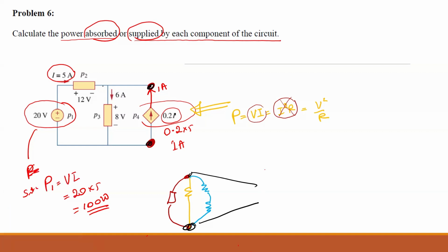It's given to us, isn't it? The voltage across these 2 points is the same voltage here because they are wires. This is the same node. This is the same node. Am I right? Nothing is in between these points. So these two are the same points. So this voltage is given as 8 volts. So the voltage across the dependent current source is 8 volts. Do you agree with that? Yeah. So that is 8 volts. Is that right? It is a supply power.